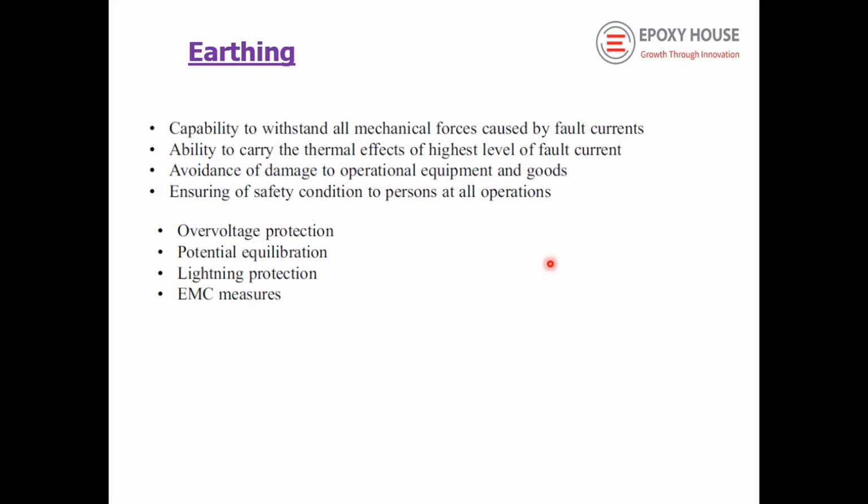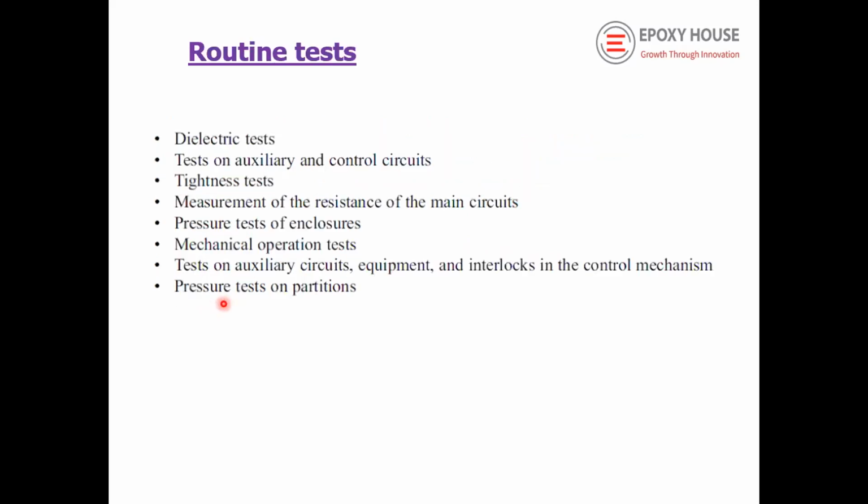Then the earthing has to have a capacity, because the complete size is reduced into a very small area. So you will have to increase the fault protection capacity. All the mechanical forces have to be taken care of, and the current transfer during the fault can be transmitted effectively to the ground. For that, the earthing is very important to have overvoltage protection, potential equilibrium, lightning protection, and these EMC measures.